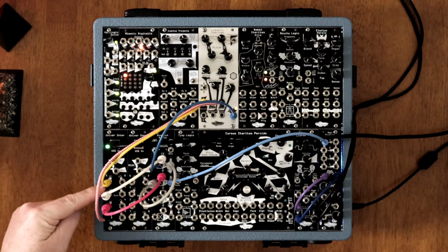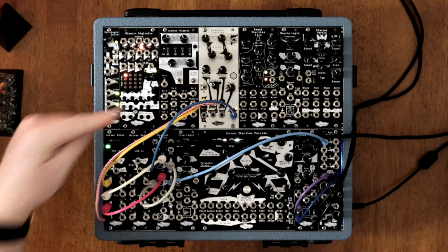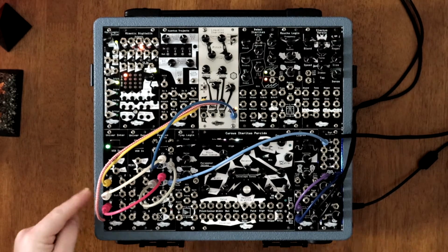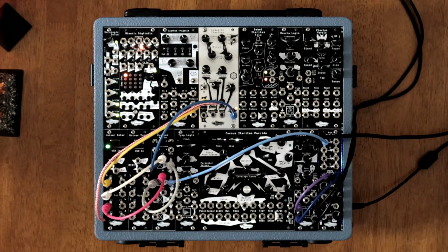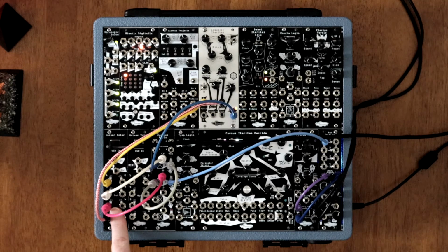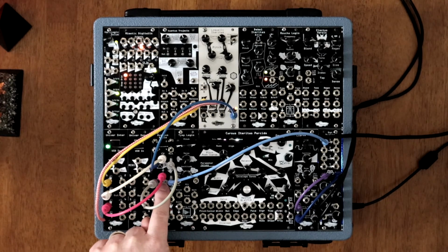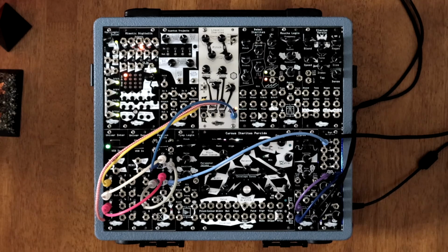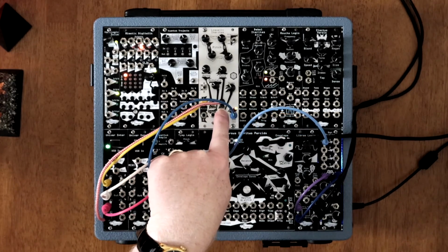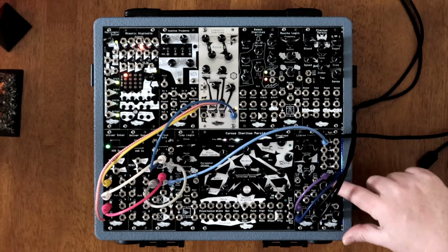Output 1's pitch will go to the 1 volt per octave on the Loquelic Iteritas. Output 3's gate will go to the first CV input on the Quantus Ampla VCA. Output 5's velocity will go to the second CV input on the Quantus Ampla to control volume. And output 7's MIDI CC channel will control the fold parameter on the Loquelic for some fun timbres.